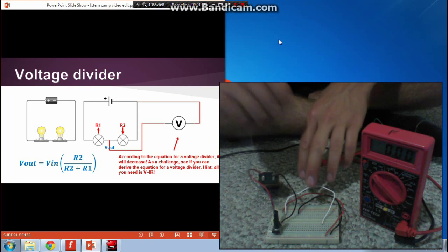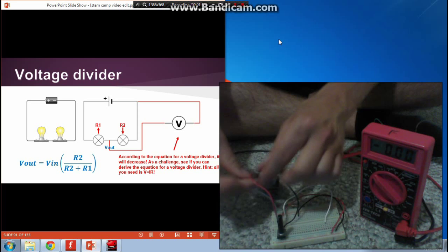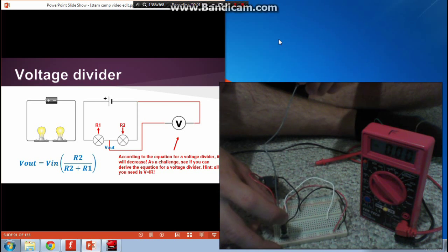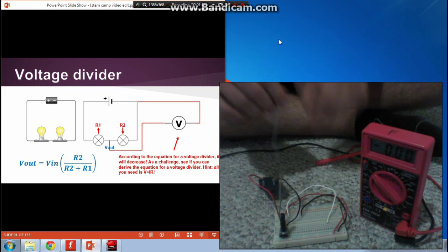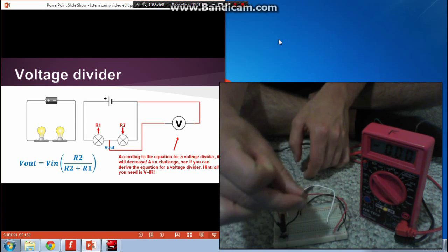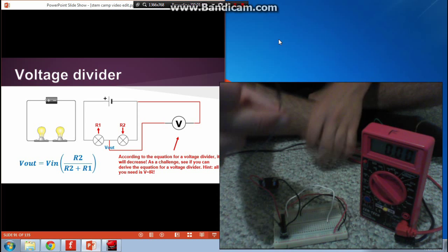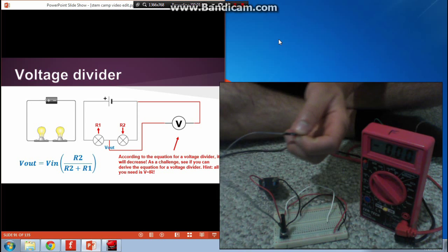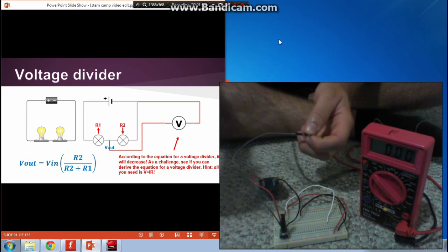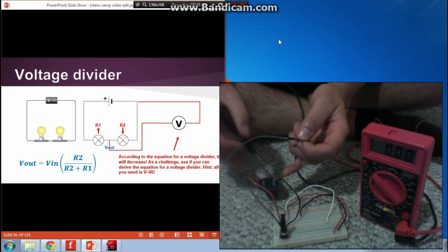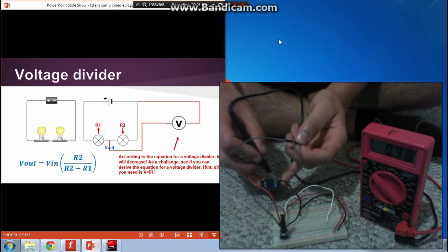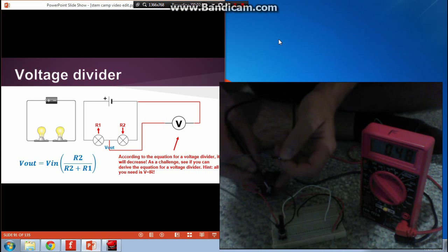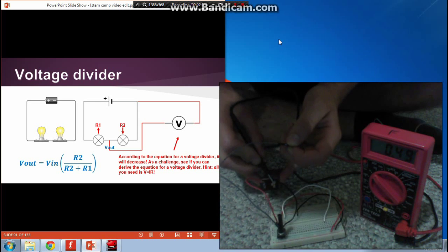So remember the center tap in between. You can think of inside this potentiometer two resistances, right? And this wire is tapping in between the two resistors. So I'm going to attach my positive lead, probe 1, to that, and I need to connect this ground, probe number 2. I'm going to connect that to ground, right? And now we're reading, okay, about 0 volts.